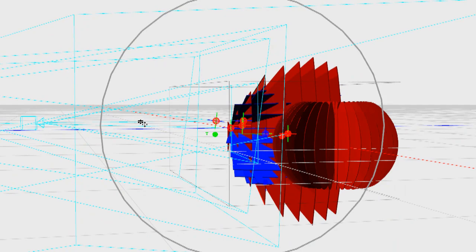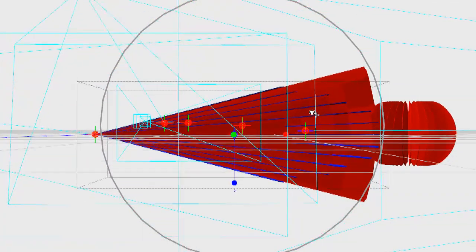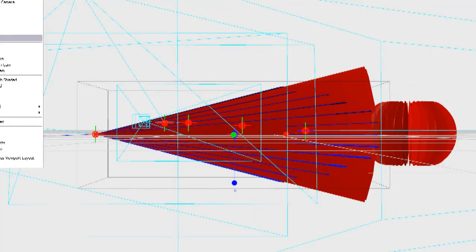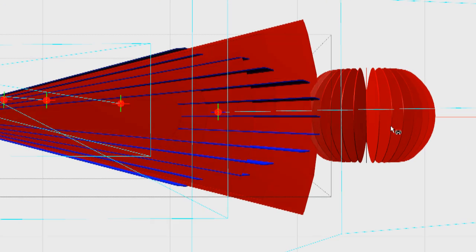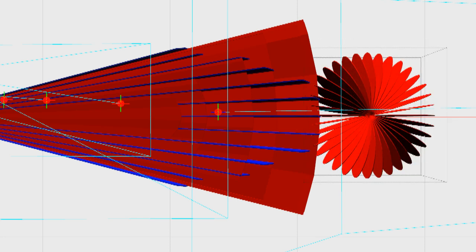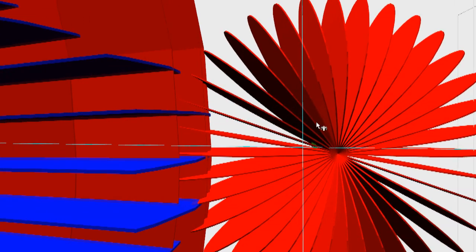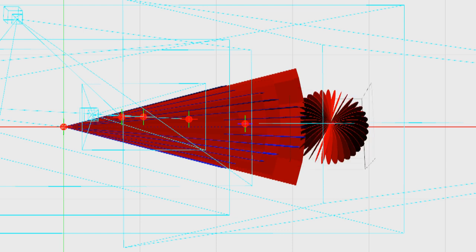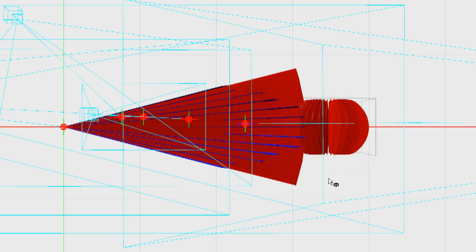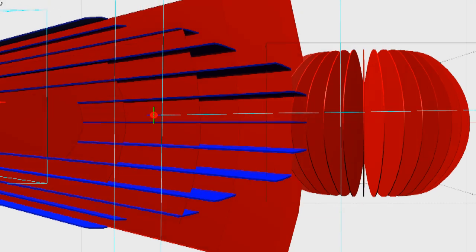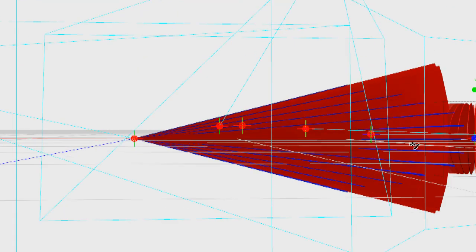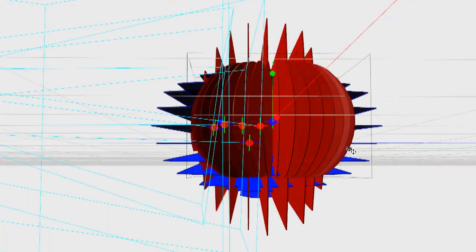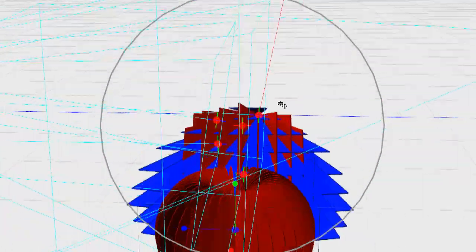One horizontal, one vertical. So this is brilliant because no matter where we are in terms of the orientation of the plane, even if we're in a hard bank roll, obviously the Yagi that happens to be mounted horizontally is getting that really nice cross-sectional area shared with the transmission of the plane, which in this instance is horizontal. And again, when we return back to forward flight, straight and level, the vertical Yagi is doing all the work.